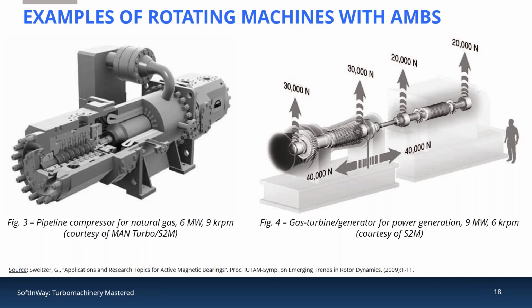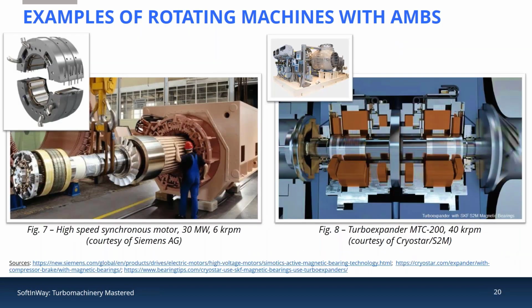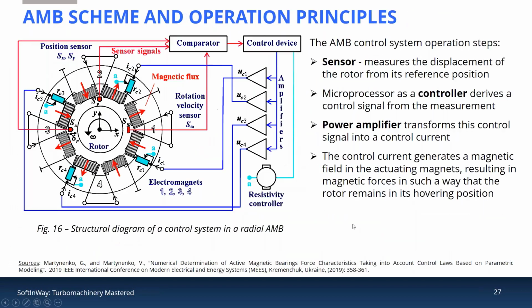Okay, thank you. Next question I have here is, how are we defining the targeted stiffness for active magnetic bearings? Thank you for this question. I tried to say it maybe not clearly. The target stiffness should be selected to avoid resonance conditions based on critical speed map analysis. Okay, I'll show you, maybe. In the slides here.